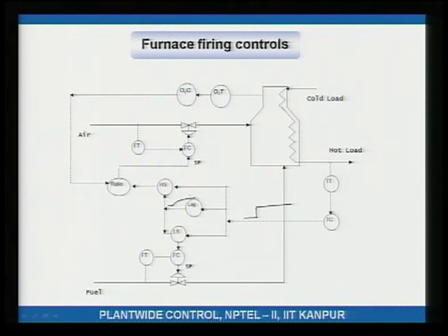Okay. Now, what you do is this exponential rise signal is compared with the low select. So, when you compare this exponential rise and select the lower of the two, notice that the exponential rise would be less than the step, right. So, therefore, the output of this would be the lag. So, the lag will get passed through.